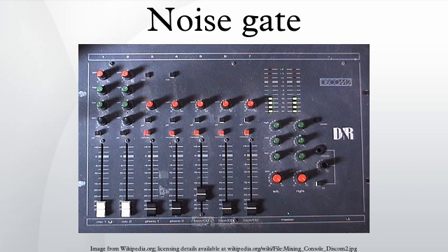This greatly reduces perceptible background noise because only the frequency components of the noise that are within the gated pass band survive. The technique was implemented in real-time electronics in some audiophile record players as early as the 1980s, and is now commonly used in audio production post-processing, where software to Fourier transform the audio signal can yield a very detailed spectrum of the background noise.